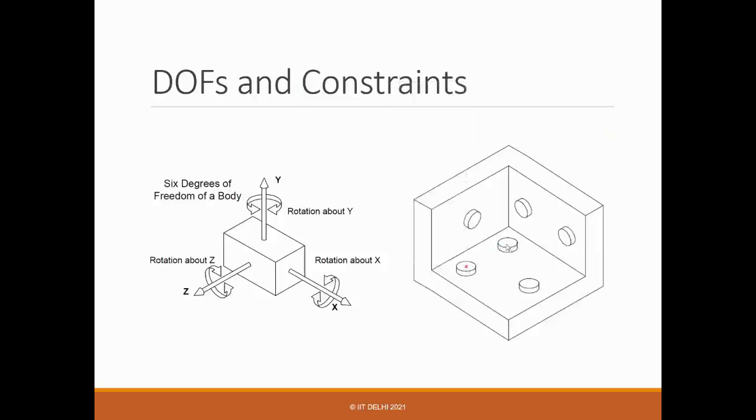So, 3 contacts I mentioned earlier. Precisely what you can do is, once you have 3 contacts, you can define a plane, right? And it's a unique plane. That's very important. So once you place this body, it's going to rest on these 3 contact points, and it will move in the plane defined by these 3 contact points, right?